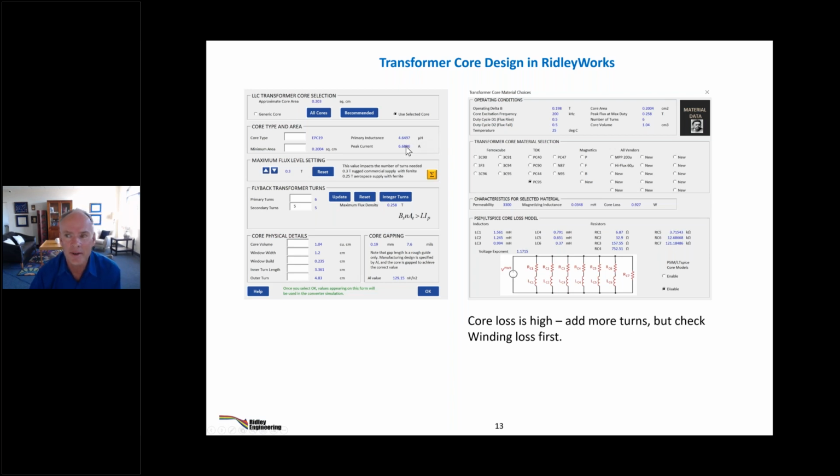There's a peak current that it's going to see during the simulation. So as you know, you've got the saturation equation of the inductance. That's what you have to satisfy. So you do a bunch of simulations, you find out what that worst case current is going to be. And then you set the size of the core and the number of turns we put on to satisfy this equation.